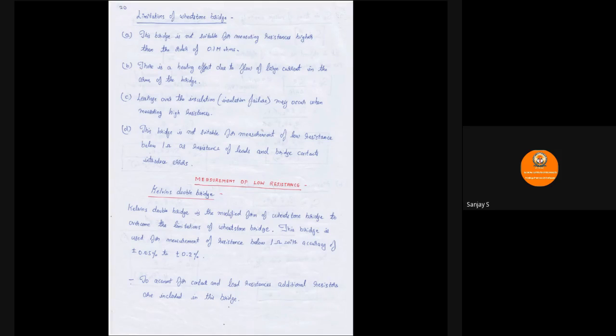So both these lead resistance and contact resistance will introduce error when you're trying to measure the parameters in the bridge, because other than R1, R2, R3, R4, these resistances also will be there. They will get added up to the actual resistances, because of which error will be introduced. So let us see how to overcome. In order to overcome them, we have to first take them into account, and arrive at some expression where we achieve the bridge balance, having them also into account. So in order to account for these contact and lead resistances, we are going to include two or three resistances to account for these. Let us see how it will be done.